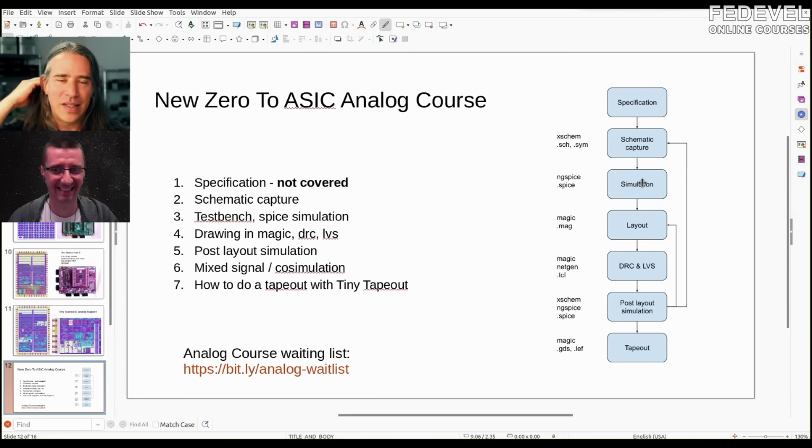The thing with Magic is it lets you do layout. Yeah, that's great. But let's say I have two pieces of metal here, two tracks going next to each other. Well, they have a certain internal resistance. They have capacitance across them. They have capacitance with the substrate, because the base of this wafer is just a sea of P doping, and it gets set to ground. So you're above that, you have a capacitor there, you have capacitors everywhere. And Magic does magic, because it takes these painted squares and it spits out a SPICE netlist with all the capacitance.